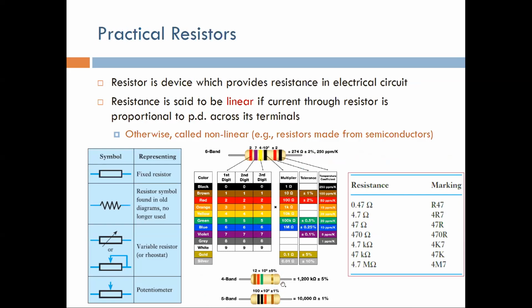If you don't have a 4th band, the tolerance we said is going to be 20%. This is one of the comments that so many people didn't follow. If you have a 3-band resistance, you can get the value like this, and you have to mention that the tolerance is plus or minus 20%. So please review this code again. If you have any problems understanding how to compute the resistors, please let me know. I put some feedback in the last homework, but if you still need some help, please let me know.